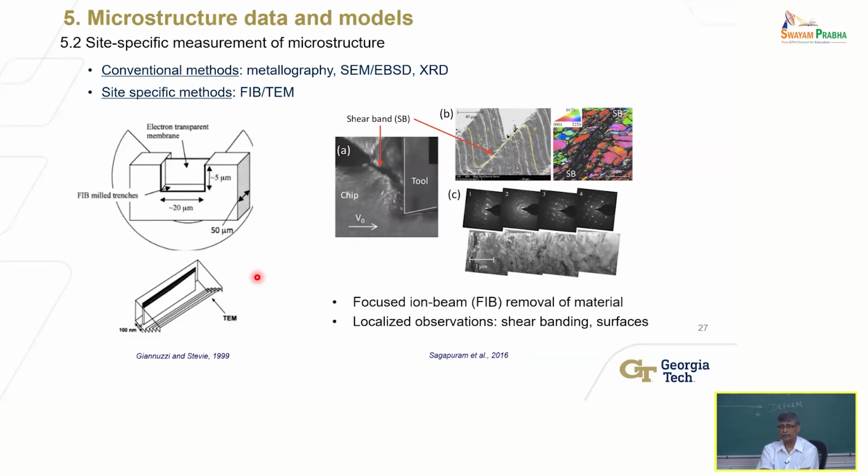The reason I struggle with that is because what you want, yes, chip formation behavior is related to how the material deforms, and how the microstructure is a function of how the material deforms, right? So yes, by controlling the chip formation behavior, you will produce a different microstructure, more than likely. So that is a reasonable, correct, accurate statement to make, right?